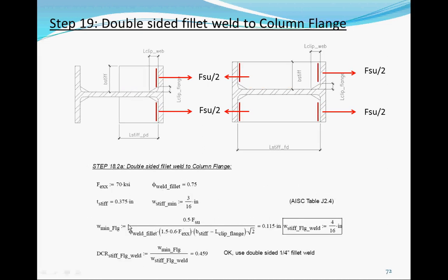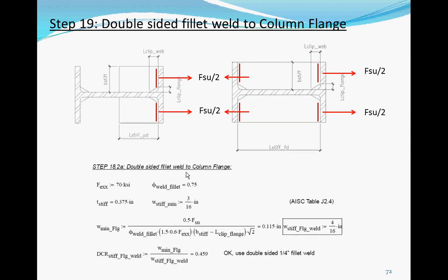Just to point out one thing, on this one I have not subtracted out yet. A lot of them typically don't like to weld all the way to the end, and they leave like a 1/2 inch either way. So you might want to subtract out after the clip, subtract out another inch. Like when you see this weld here, they don't go to the end. So we're counting on the whole width, so you'll need to subtract out each side. I would say one inch, so half an inch on either side.